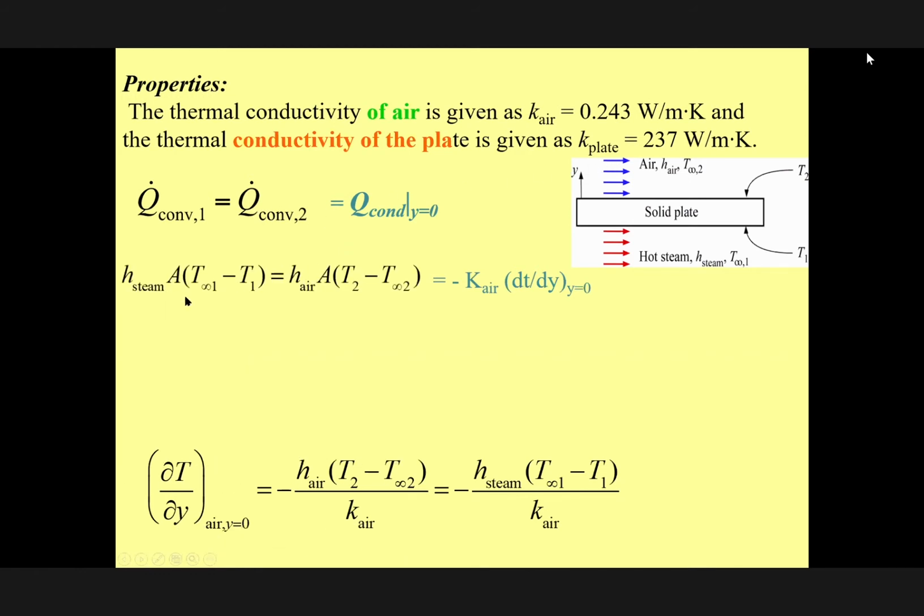And if I put here, convective from here to here is represented by this one. Again, H of steam, the heat transfer coefficient, times the temperature of the fluid minus T2, okay? Because the fluid is 100 degrees, this is 80 degrees. And H, we know that. And this is the same because it's steady state, therefore the same amount of heat goes from this plate to infinity. Therefore here it is T2 minus T fluid. And that's exactly the same as the amount of conductive heat transfer through the thin layer of the boundary layer that we have here, okay?